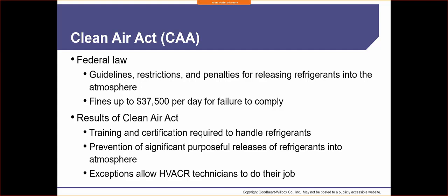So the results of the Clean Air Act: training and certification required to handle refrigerants. Yes, EPA licensing. We need to be EPA certified in order to handle refrigerants. So that doesn't mean, hey, my boss called me and he needs me to bring this jug over and I need to be EPA certified. No. What that means is I can't hook up my gauges to a system without having that card. If I don't have that card, I can be fined, all right? Or your boss can be fined, or anybody else.